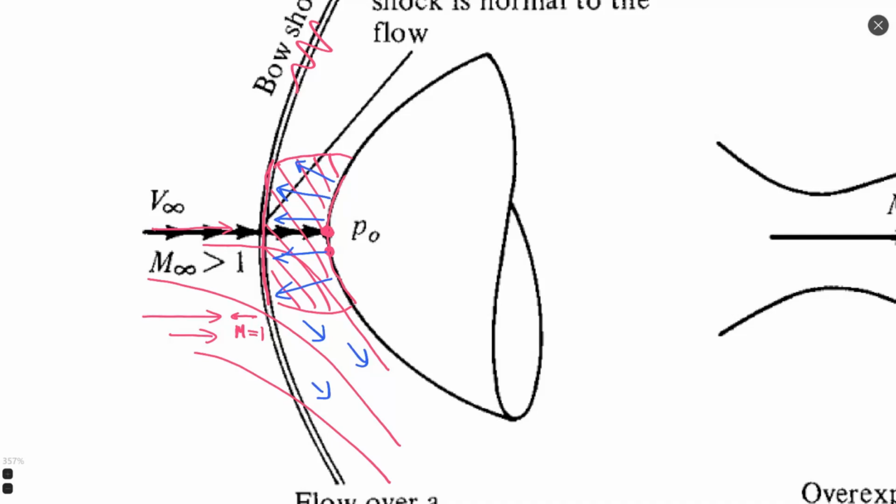No, we do not use average values on such a transition, and the theory says that it's more convenient, and correct, to see parameters before and after the shock wave, not to see parameters inside shock waves.